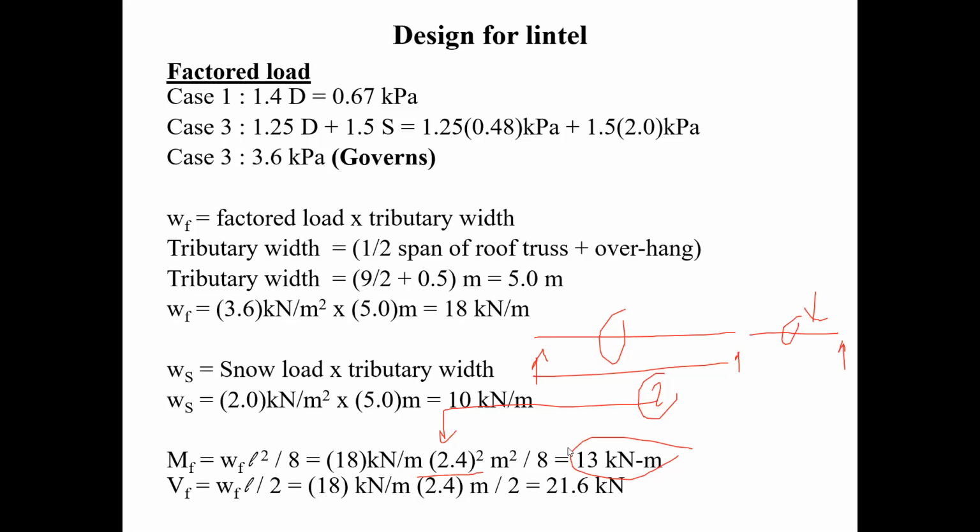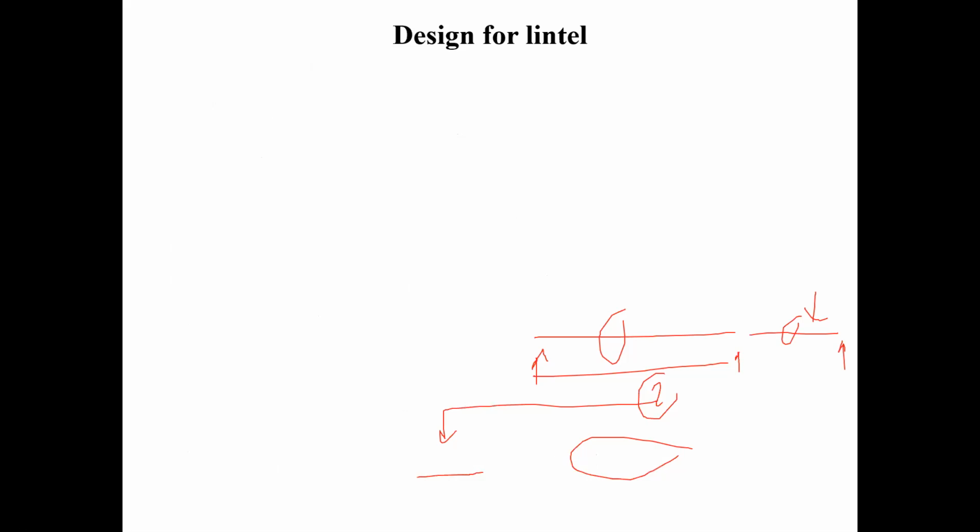And the last thing I need when I go to select the beam from the built-up beam table is, of course, my EI value. So there you go. I want to keep the deflections to L over 360. Why? Because on the inside, over that beam, that wall, there's going to be drywall, and therefore I want to minimize the cracking of the drywall that's going to be installed on the face of the beam.